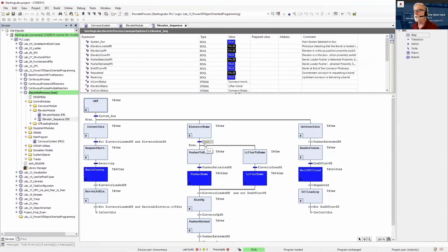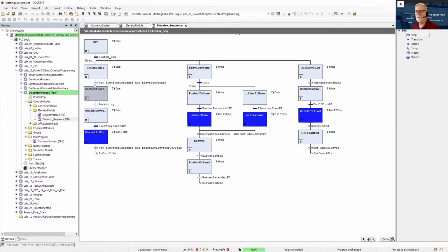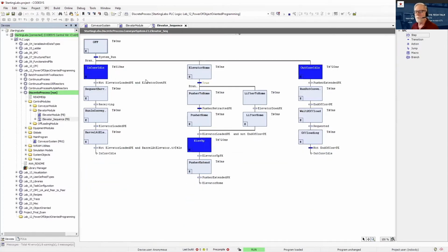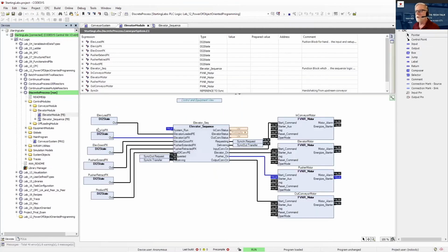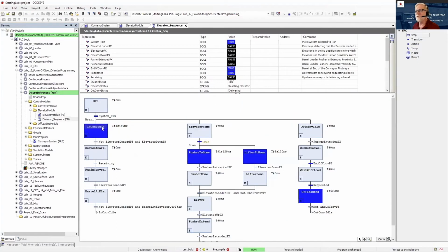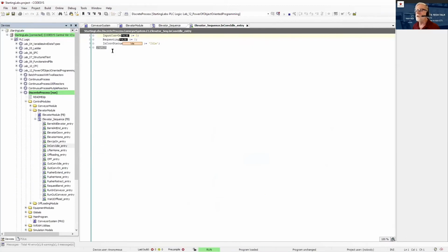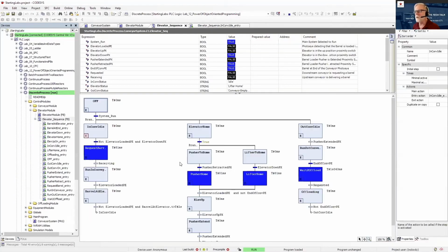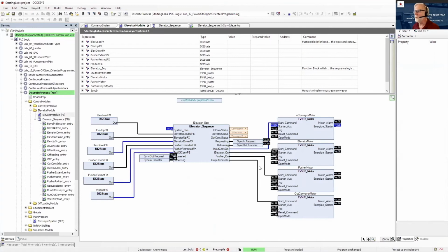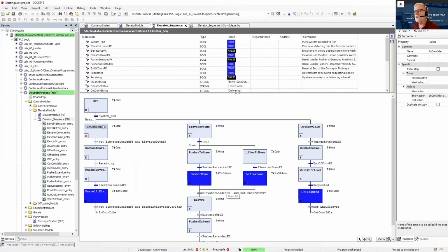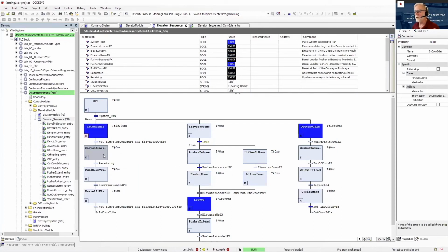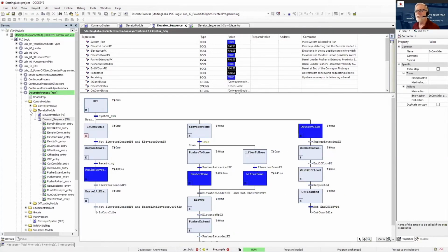So we can actually look at the control code running here. It's a sequential function chart. Now those inputs that we saw, right? All the inputs are the transitions. They drive the transitions. And then the outputs are all in these entry actions, and they drive the outputs. Each state drives the appropriate outputs for that state. And this one has a parallel sequence, so they actually have 3 different state machines going on simultaneously. Now let's take a look at,